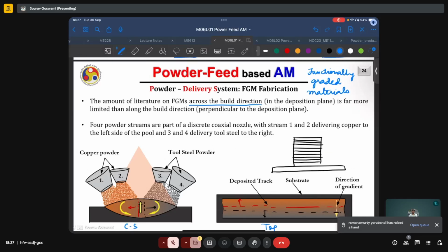It is easy to have different materials across these different layers, because when we are switching from one layer to the next, when the head is lifted and there is no deposition going on, that time can be utilized for switching the build material or switching the process parameters and so on.